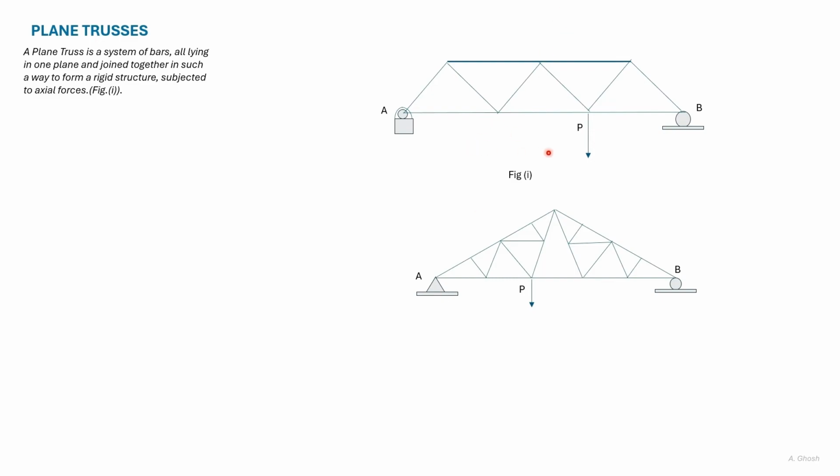The truss on the whole is in equilibrium, and each of the bars in the truss are also in equilibrium, and each of the hinges are also in equilibrium. The reactions of the bars of the truss are equal and opposite to those exerted by the joints. The common line of action is the axis of the bars.